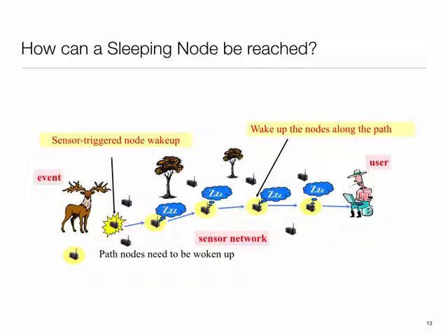They're anyway low power radios, so there's not a whole lot of headroom remaining in that process. Another issue is that these wake-up radios usually work by monitoring energy in the spectrum. They ask, is there some message going on? If so, there is some RF energy, and I'm going to wake up. The problem is that there is often spurious RF energy, so you keep waking up falsely, and that negates the purpose. So it's a complicated thing.